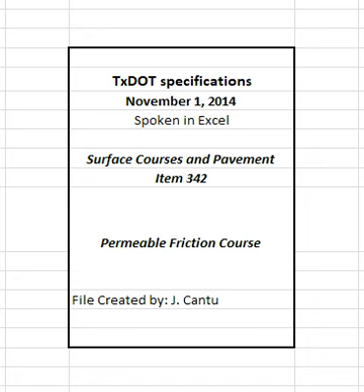4.2 Reporting and responsibilities. Use department-provided templates to record and calculate all test data, including mixture design, production and placement tests, control charts, and thermal profiles. Obtain the current version of the templates at http://www.txdot.gov/inside-TxDOT/forms-consultants-forms-site-manager.html or from the engineer.